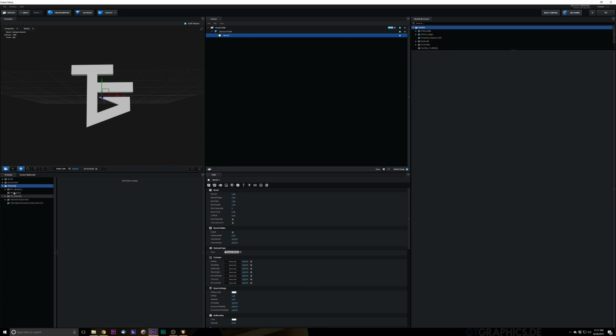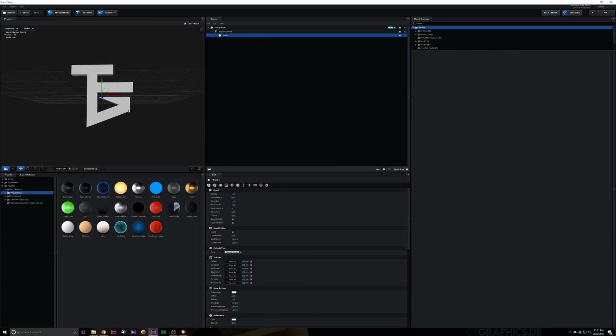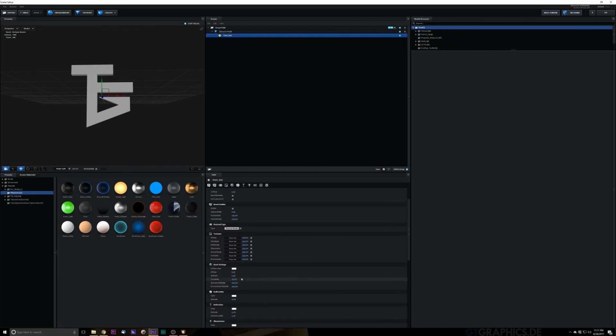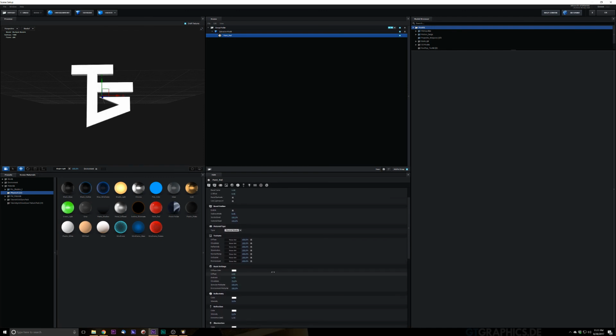Let's do materials, physical materials. Let's put this red on there, but I don't want it to be red. I want it to be completely white. And I want it to be diffused a fairly good, okay amount. Yeah, we'll just turn it to 1. Glossiness. I do want it to be quite glossy. And reflective. I do want it to be reflective. But I want my environment multiplier to be down because I don't want to see it.